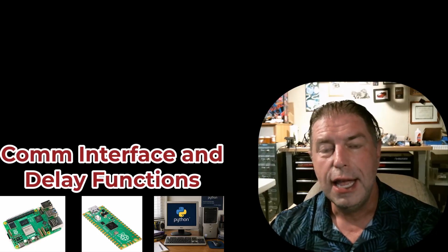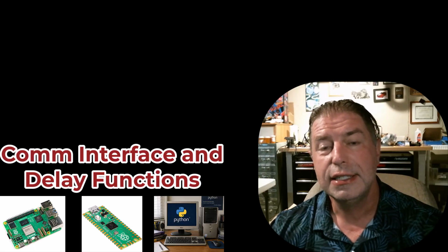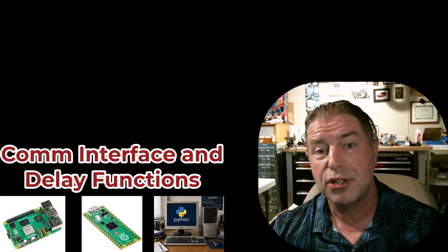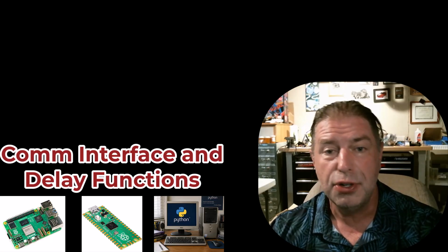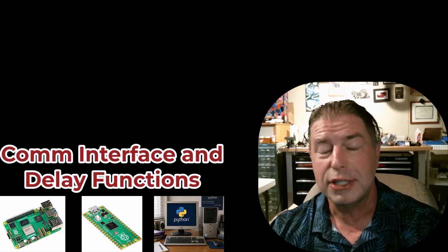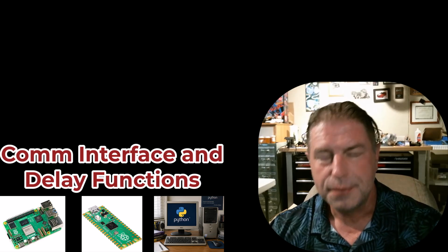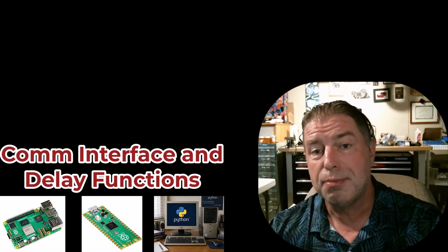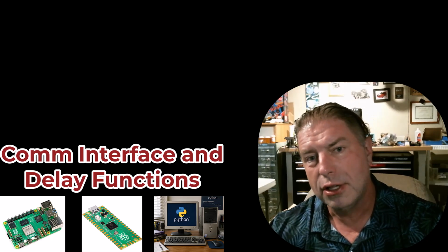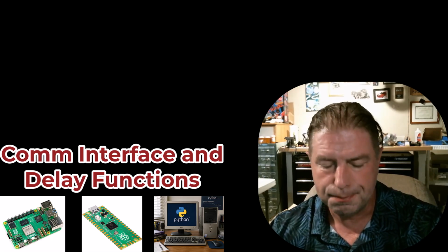The Serial Wombat Python library is a layered library. At the very bottom is an interface file, and that interface file is used to hand off packets to and from the Serial Wombat chip. And maybe that's over UART, maybe it's over I2C, maybe it's over a UART to I2C bridge. In the future, it's possible we may also support sending packets over TCP/IP or something like that. And all of that is abstracted.